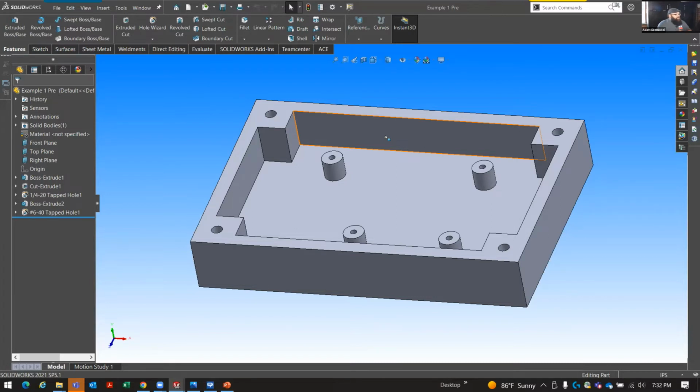Yeah, we could probably cut this if you do a sinker EDM. If you really want to, have a counterpart made out of brass and do a sinker EDM to get the exact cutout that you need. Yes, it's doable, very expensive. You're looking at $10,000 or so for one piece of billet. Diminishing returns. But you can 3D print it, correct? A 3D metal printer, but again, still very expensive. At some point, you've got to look at your diminishing returns.